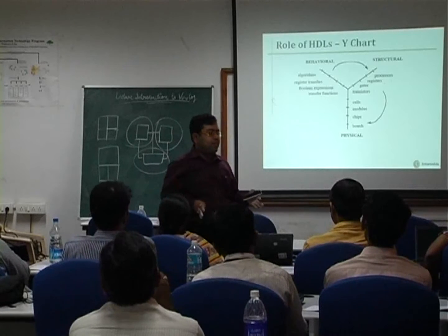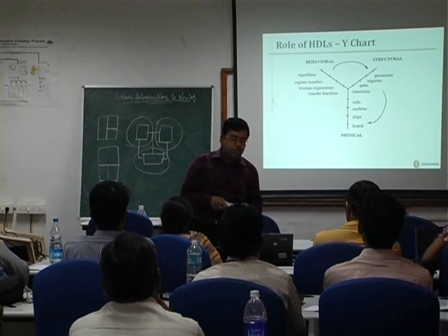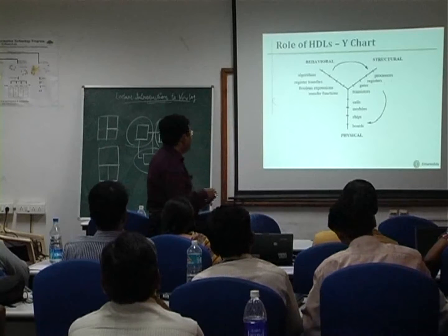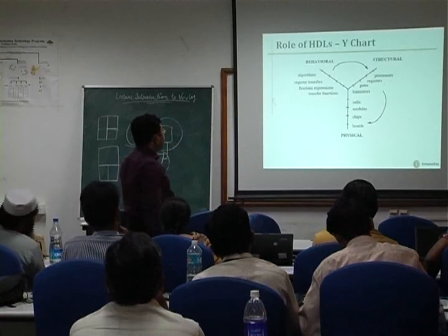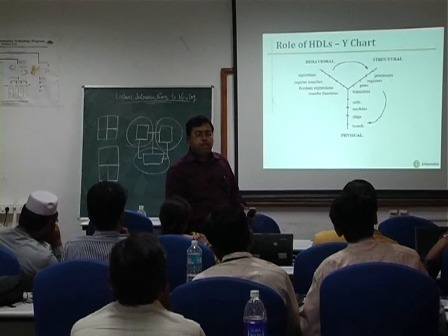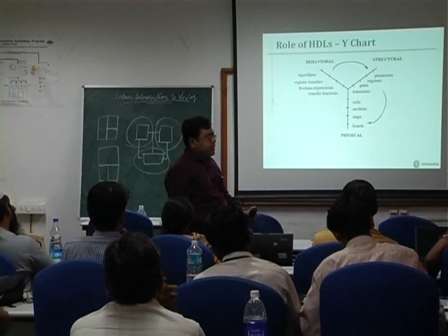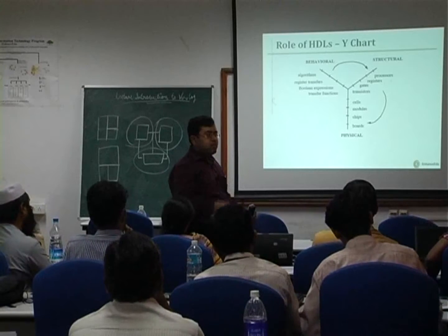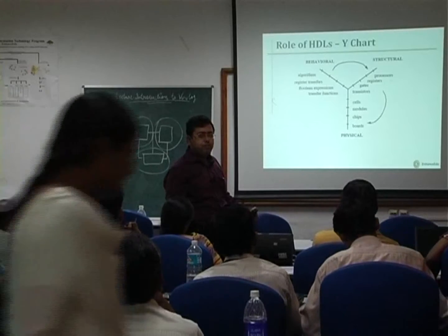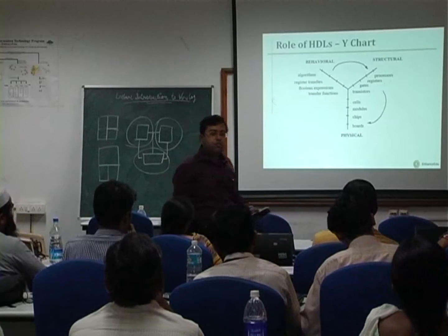Then below the register transfer level, we have the gate level, for which in the behavioral dimension we express it in terms of Boolean equations, and at the structural level we express it as an interconnection of gates. That is how the spiral model keeps on flowing. Ultimately you arrive at the intersection of these three dimensions. That leads to rapid prototyping of the system. While a team of people are translating a description from one domain into another, another team can start the next iteration. That leads to an increased speed in the design flow process. However, you need a large team to implement the notion behind Gajski's Y chart.